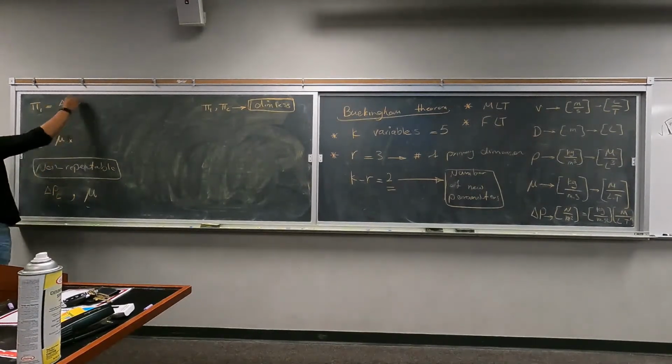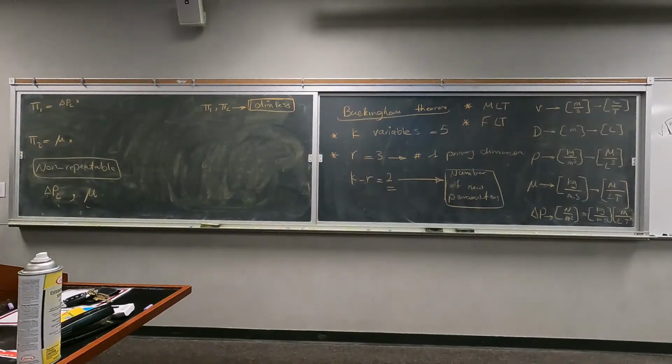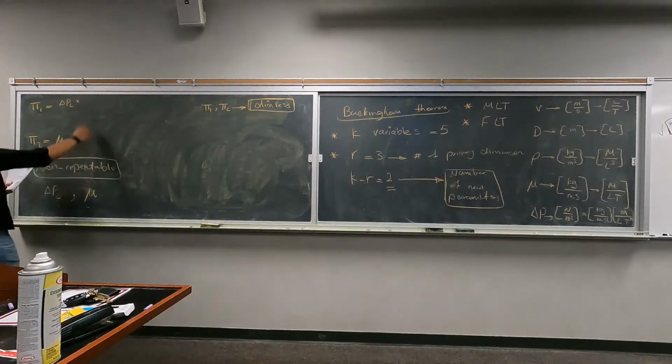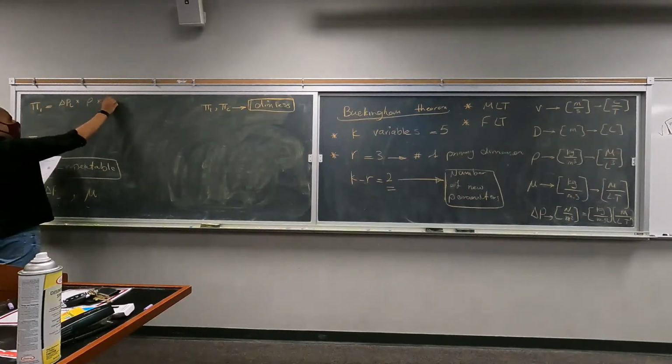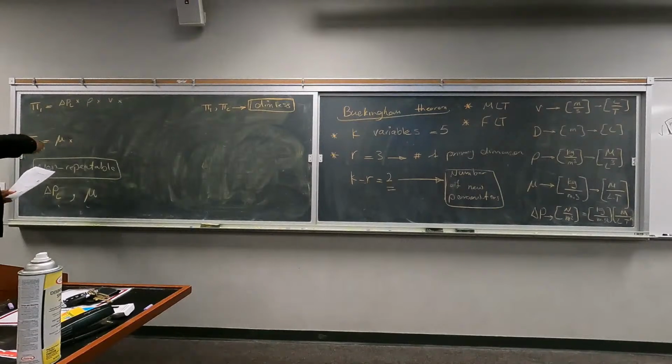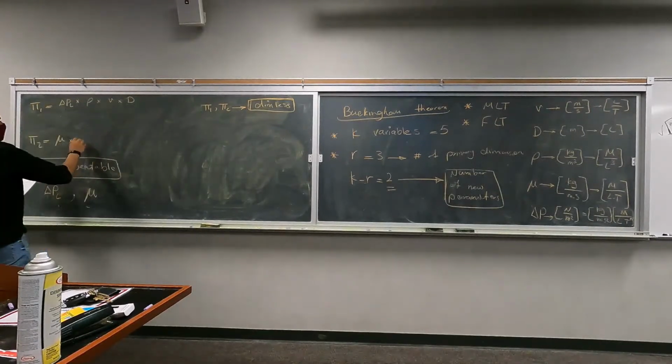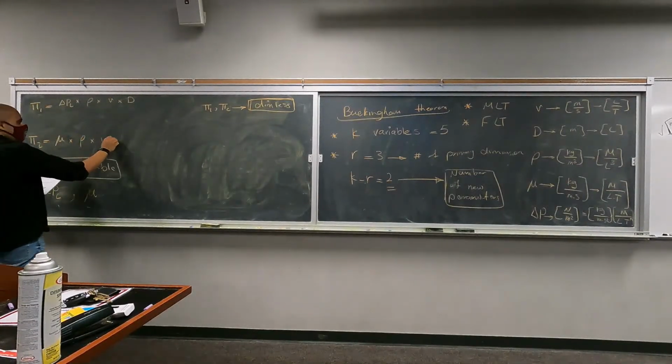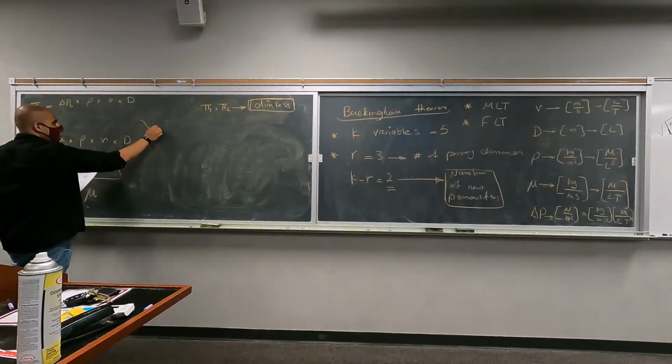Or their power actually can be 1, 2, 3, 4, 5, whatever. The only thing that matters here that we are setting is that viscosity has to be present in one of the pi's, and pressure drop has to be present in the other pi. Okay, what are the other parameters we have? We have density, we have velocity, and we have diameter. Same is true. And these 3 are called the repeatable parameters.